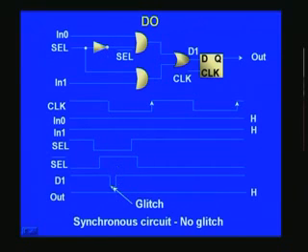Now if you had processed this elsewhere without the flip-flop, what will happen? It may so happen that when your circuit is sampling, it may sample at this point, and that is not the desired point. You wish to sample only when the actual D1 is high, but you might sample here without your knowledge. So that will play havoc. Had you given this as a clock input for some other circuit, I don't have to tell what the implication will be. And therefore it is very essential that we get rid of this glitch at all costs.